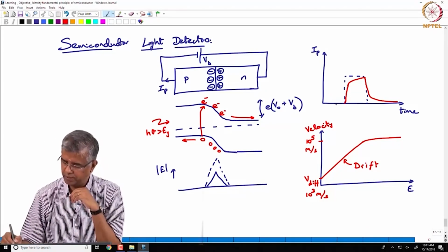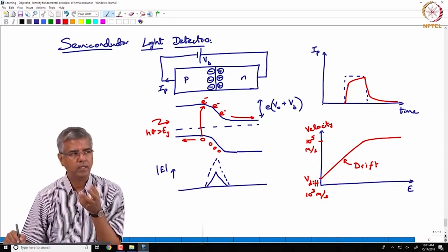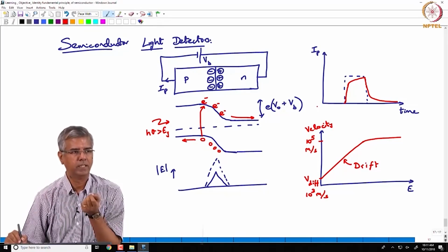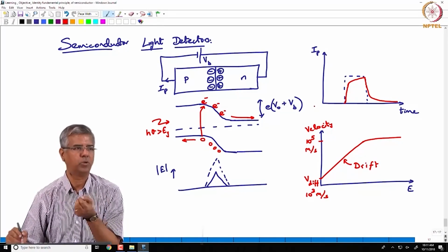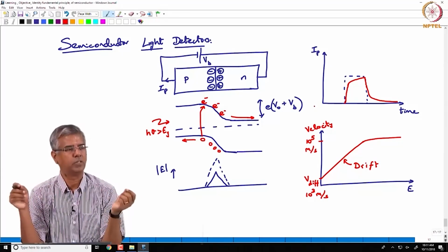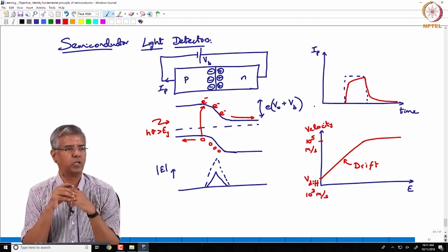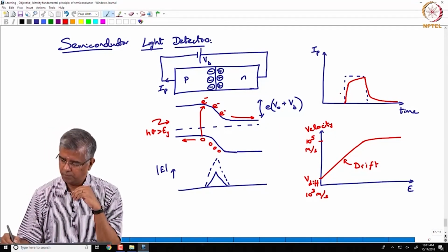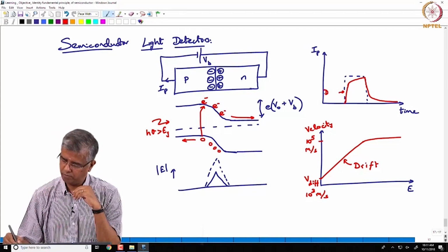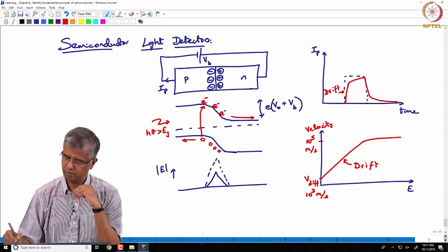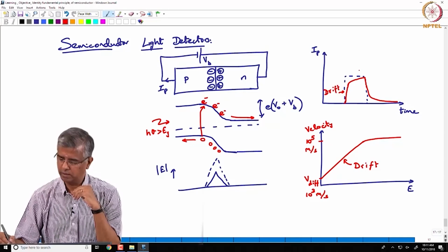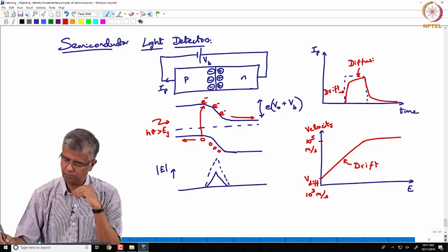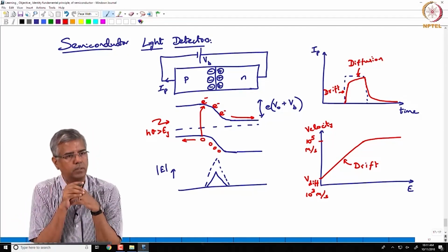Now, clearly we say that any charge under the influence of the electric field is going to have a higher velocity. So, those are the charges that you are going to see come out of that going to contribute to the external photocurrent, right. So, in this region we have drift and then this slow response actually corresponds to diffusion, right.